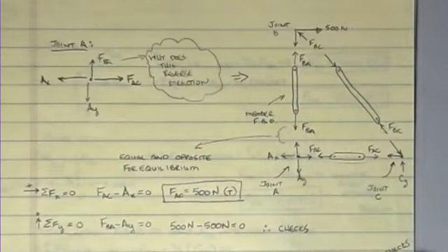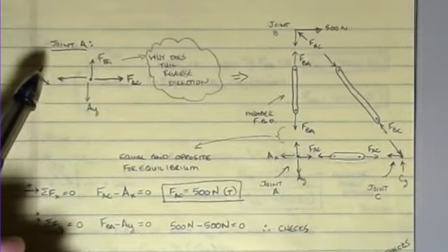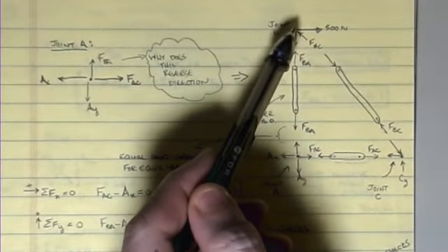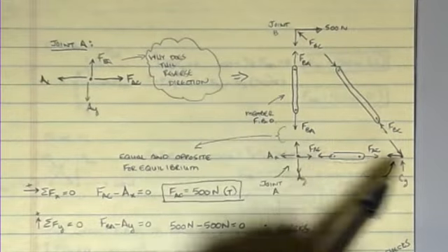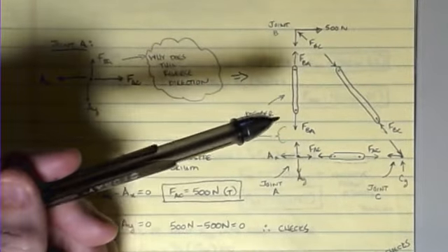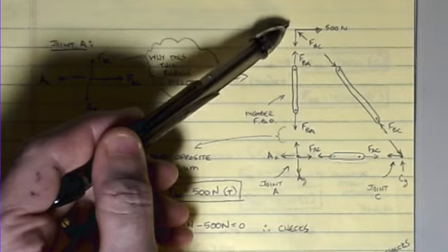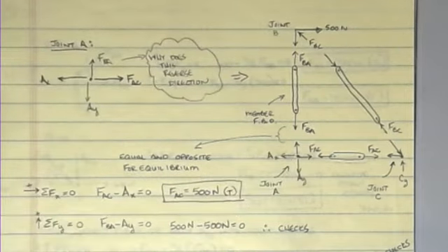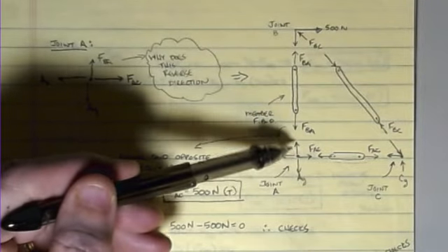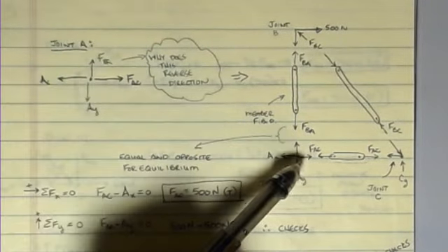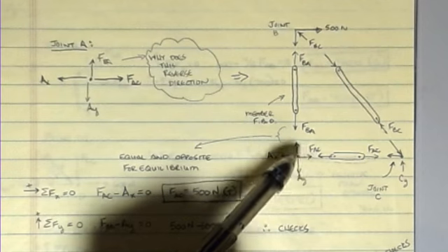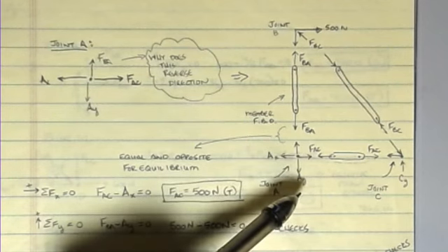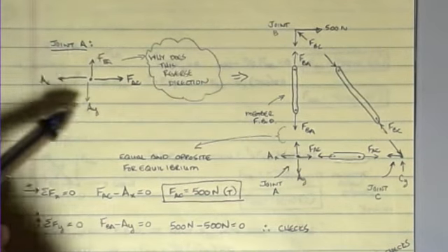What we've done is draw the free body diagram for one specific joint, and that was this joint B up here. That's the one we just did. But if I look at the whole system together, you can see how everything's balanced. Here's joint B that we just drew. If I jump down to A, I would get a picture that looks something like this. I get a force pulling on this member and a force pulling on this one. So I've assumed tension on both of these, and then AX and AY are obviously the support reactions that we have. That's the picture we've drawn here.